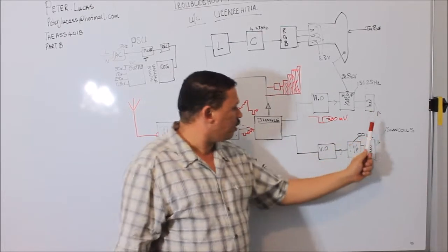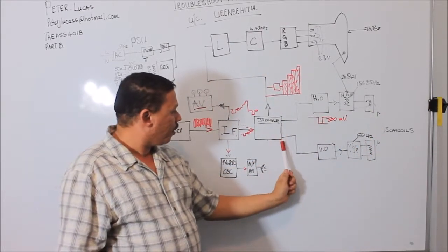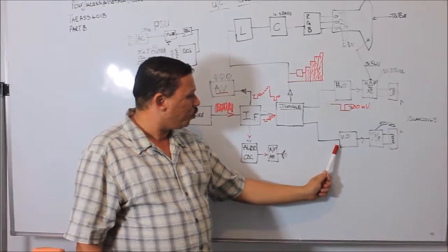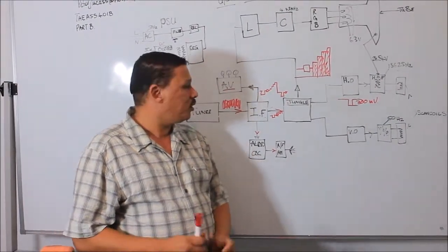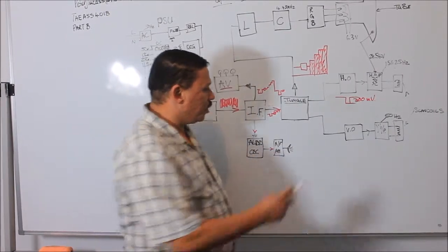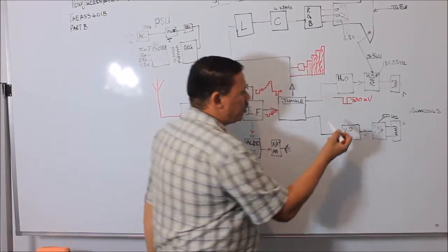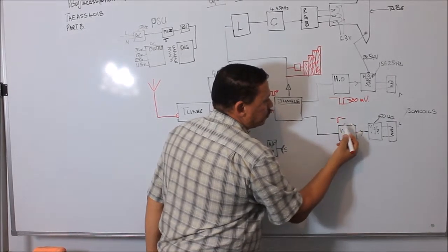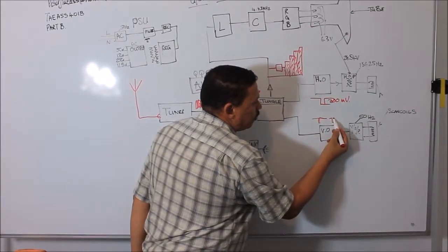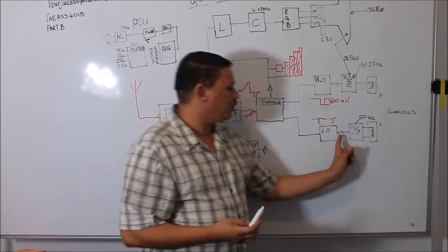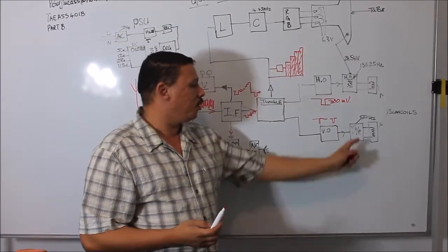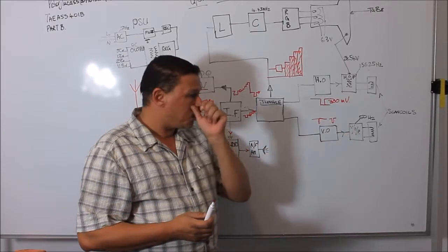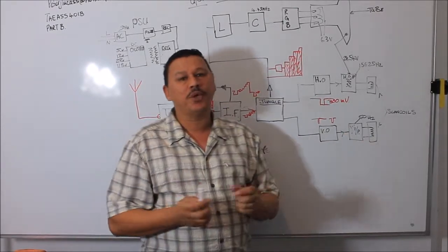So let's feed it a little bit back. We come back to the jungle chip. The other output, which is also very important, is the vertical oscillator. The vertical oscillator also looks like a sync pulse, but it's just very small. After the vertical oscillator pulse, it goes into the vertical output circuit. The vertical output circuit is responsible for the frame of the picture.